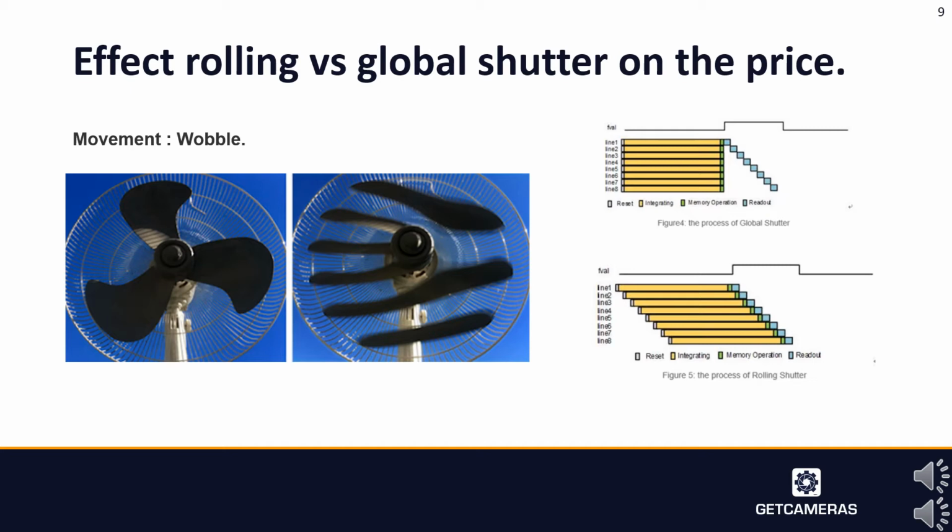The idea is to capture the image only when all the lines of the rolling shutter sensor are exposed at the same time. This requires a dark environment and an LED light with a strobe controller. Because the setup needs hardware and resources, and time to deploy it, this is not always worth the effort. But remember, there is a possibility to use a rolling shutter as a global shutter to save some money.